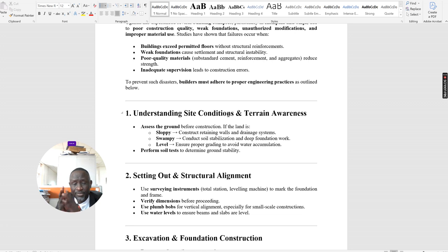So with manual excavation, that's where experience is very important, or the use of DCP testing and site investigation, where you do drilling to ascertain the firm ground. Understand that most of these buildings are site specific. A building in a swampy area will never have the same foundation as one on a hilly area, a flat area, or a rocky area.